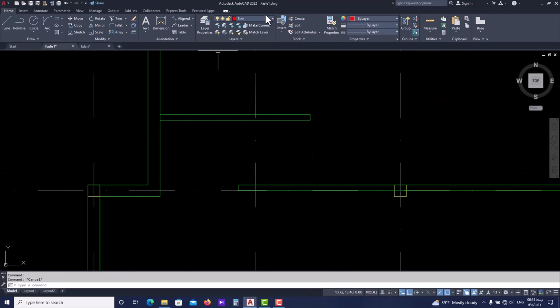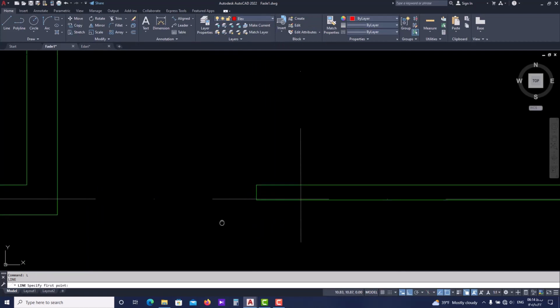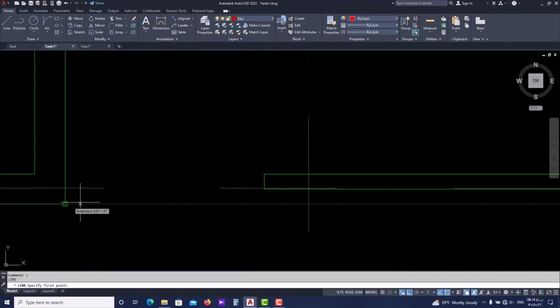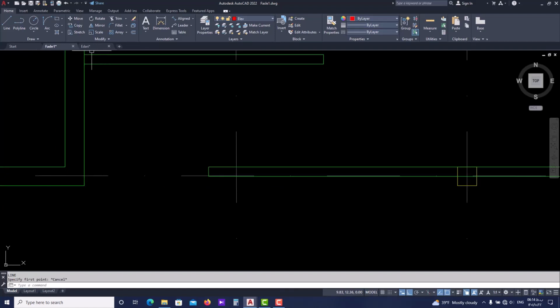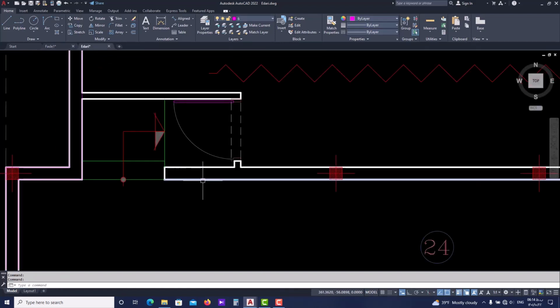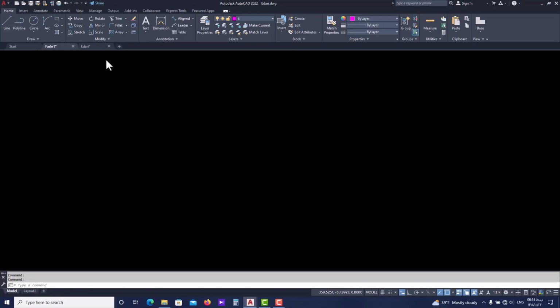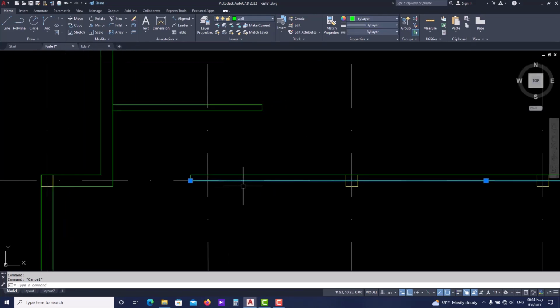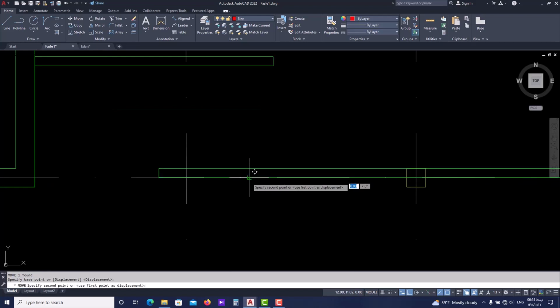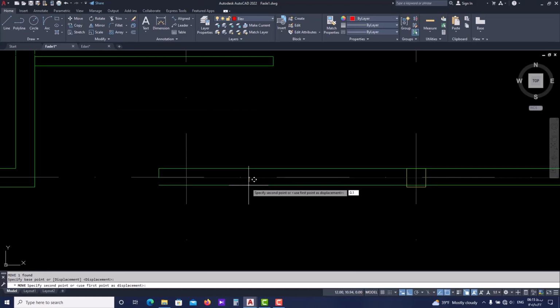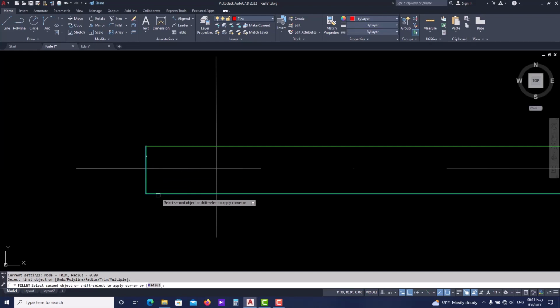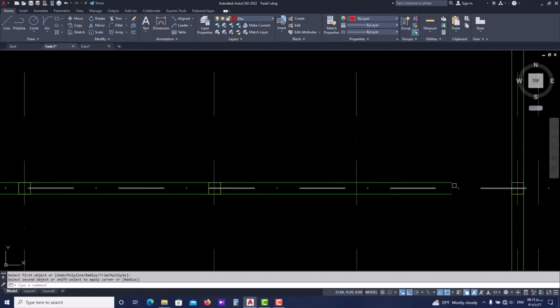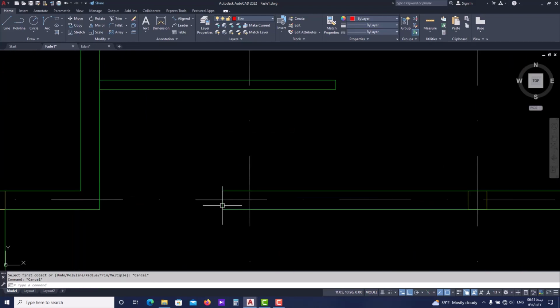Okay, let's move it in the elevation layer, right, and enter from this part. Let me actually see if I'm doing this correctly. Oh, this is actually 20 cm. This is not 10 cm. All right. So we can just select this, then enter, move it down. Then we can use fillet to connect these lines. Then use line, enter to draw the stairs.